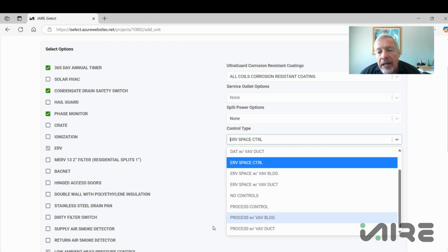It allows us to select a unit whereby we can run the full complement of cooling and modulated hot gas reheat along with wintertime heat at the same time. And think about that from an electric unit standpoint. We might have to run compressors and electric resistance heaters at the same time, right alongside the modulated hot gas reheat. We could have everything in operation at one time. We call that process control. And when it comes to a specific process, it is allowed under energy code.